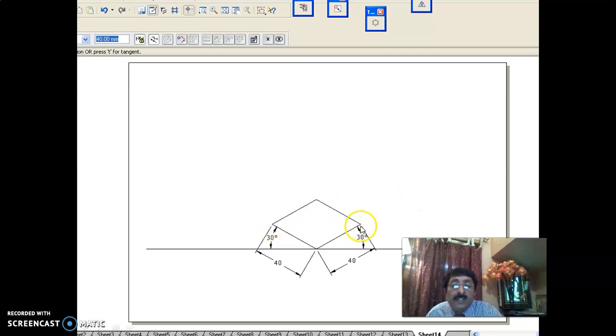But this isometric pyramid will have an apex and you will have slant edges here. Slant edges are non-isometric because they are not parallel to PP, QQ, RR, SS, what I mentioned earlier in session 1. Vertical edges, it is not parallel. Slant edges are all non-isometric. That is why you draw a mid to mid line to get the center here.